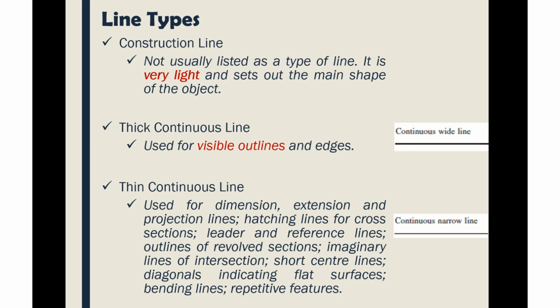It's not to say that after doing your construction line that you should clean it. If you do that, there is no way that you wouldn't know, and at the same time, it will make your work rough. So please, your construction line should be made as much as possible not visible to others. It should be very light.